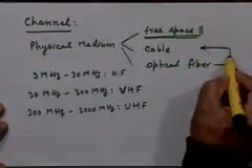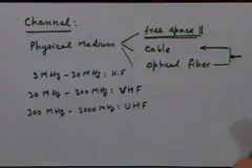Some of these issues I will discuss in the next class about free space propagation, but briefly, these two, cables and optical fiber, are the easier kinds of mediums to work with. Cables are typically coaxial cable or a pair of wires. They are typically much cleaner media as compared with free space, and therefore the performance you can get here, within the bandwidth limitation of the cable, of course, is much better than what you can get in free space.